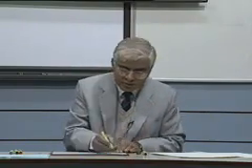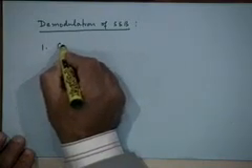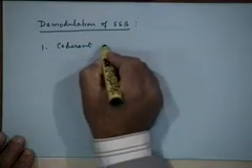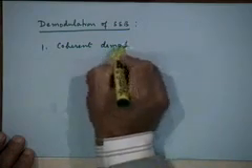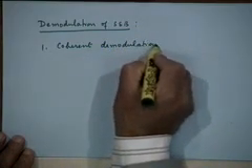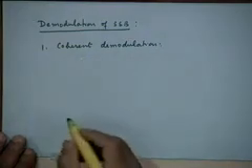The demodulator that I have discussed so far, at the beginning of today's class and also mentioned earlier, what kind of a demodulator is that? What do we call it? A synchronous or coherent demodulator, right, which would require us to have a local carrier in phase synchronism and frequency synchronism with the carrier of the incoming signal. So one demodulation process is the coherent demodulation that we already discussed.